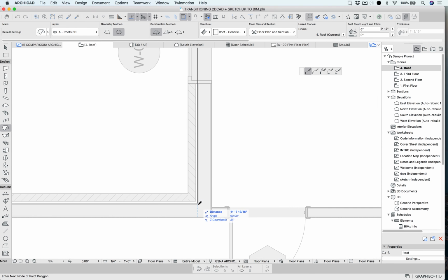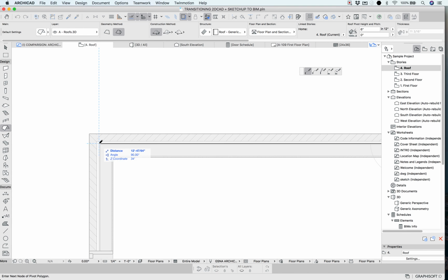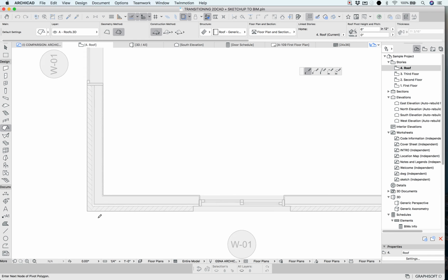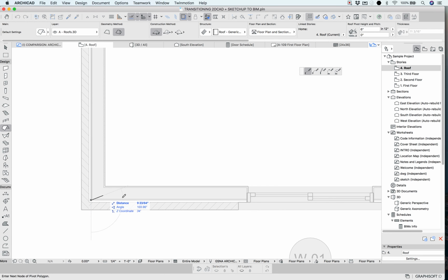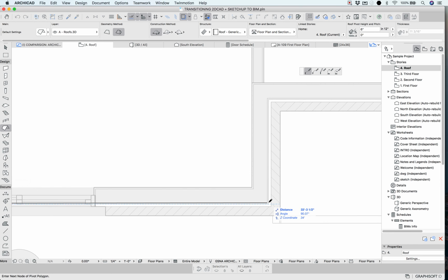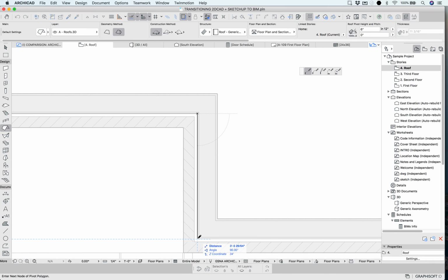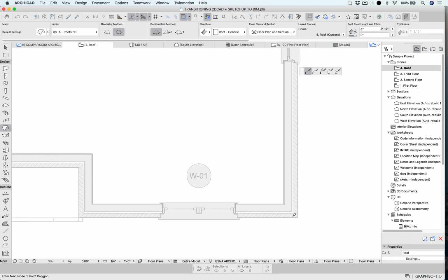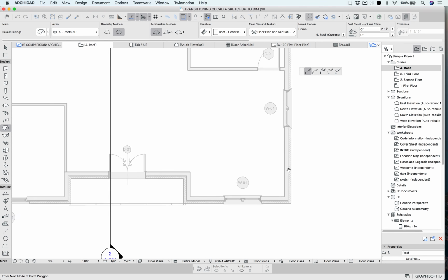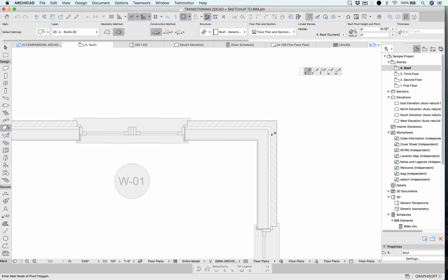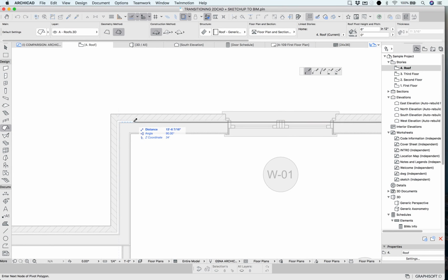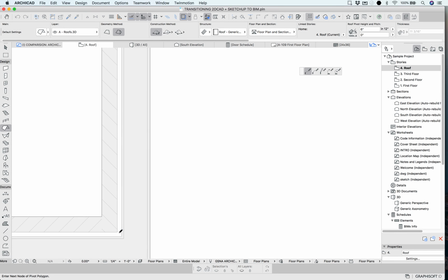And so as I'm moving around the building here, and just let me finish up these corners, it's going to figure out the geometry that's best based upon the shape that I'm drawing. But if I just want to draw it one plane at a time, each roof plane at a time, I can do that as well. So you always have options in how you create, what you create, and how you go about drawing it here.